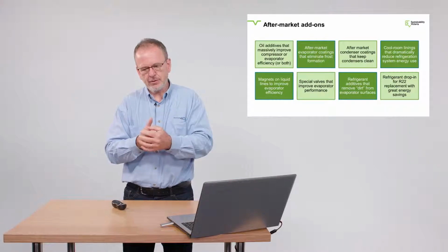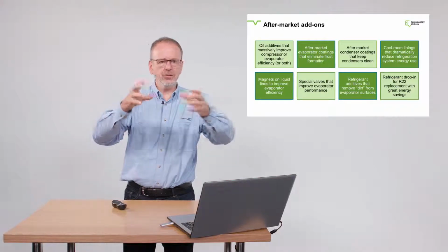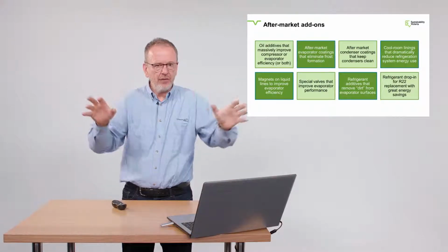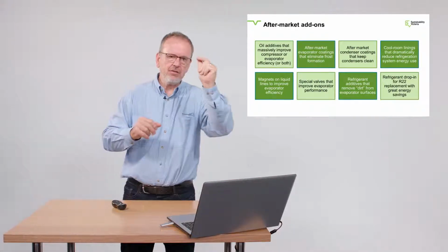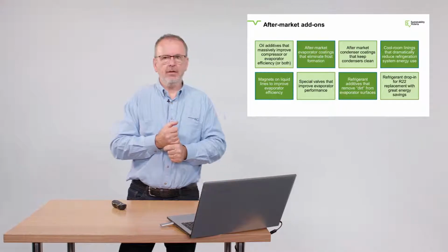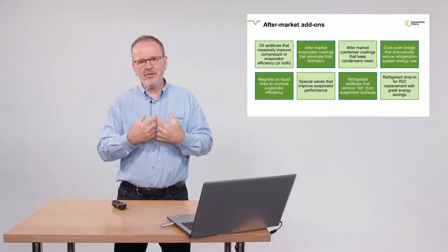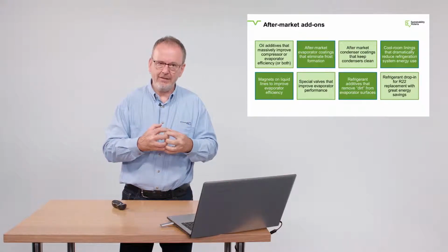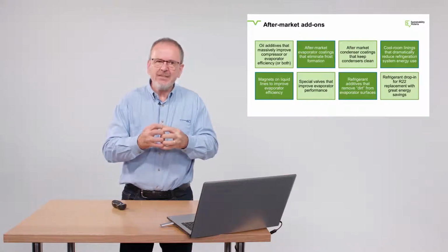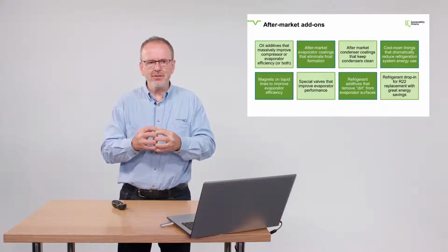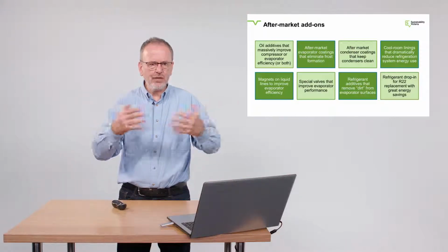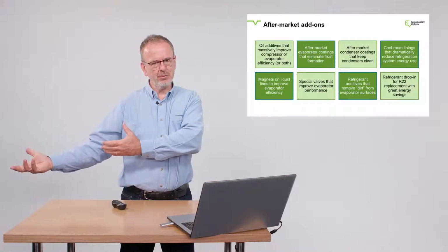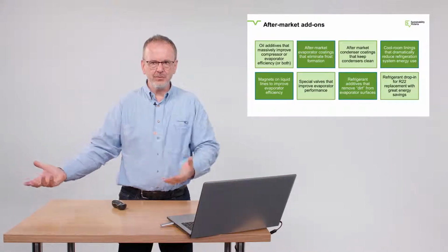The latest was a drop-in refrigerant where, R22, the one refrigerant that is now completely phased out, still a lot of it around, you can buy this drop-in which gives you an instant 30% energy saving. Now, as a thermodynamics guy, that really annoys me because R22 is actually one of the best refrigerants we've ever had. It is really hard to build something as good as an R22 system. Everything is less, all the other new gases are not close to it. And these guys come up with a concoction which is 30% better. Like it's not even possible.